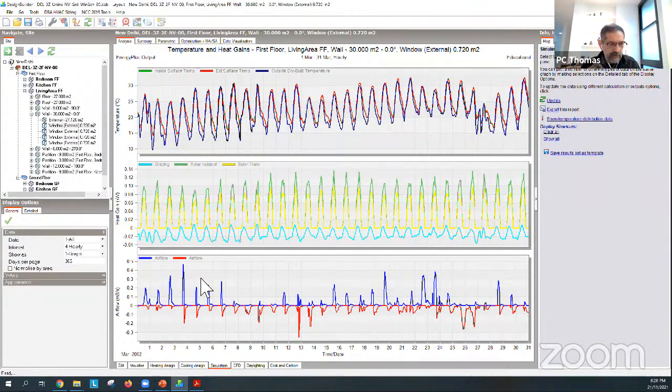Just remember, when you switch on surface and subsurface data, it creates a really massive file, and to load it up takes a lot of time. So I seriously recommend that you use it for testing your design at certain points. You do a week, 2 weeks. That's sufficient for what you need to know, and the model will load earlier. Okay, there's some things here telling you the inside surface temperature of the glass and the outside surface temperature of the glass compared to the outside temperature, right? So some of those things are useful to see.